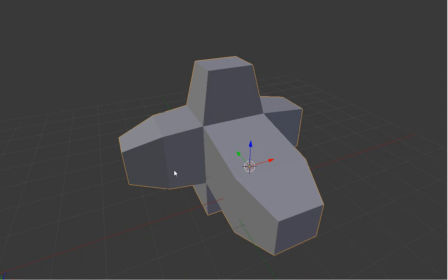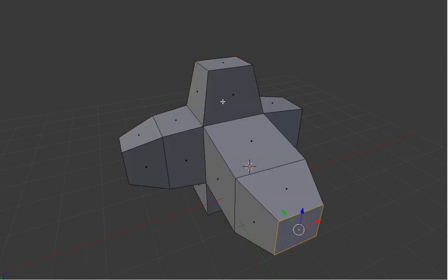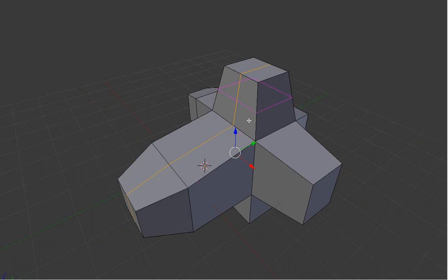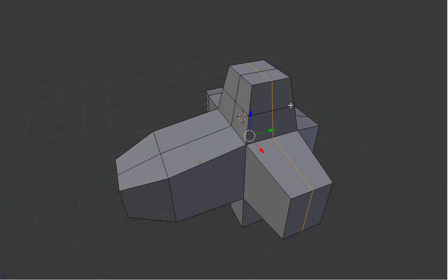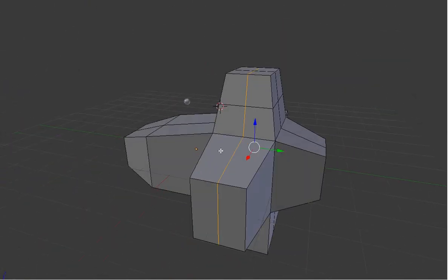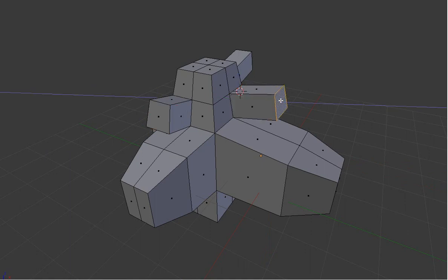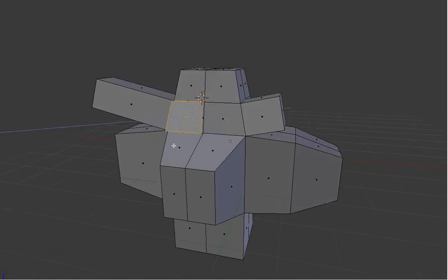One more tool is the slice tool, or in this case in Blender it's called the ring tool. So it will go round your object, it will loop round your object wherever it's placed, and it will add more edges in your object so then you can go to things like extrude again, extruding the polygons, and then it will do stuff like this. So it's pretty good, pretty good.